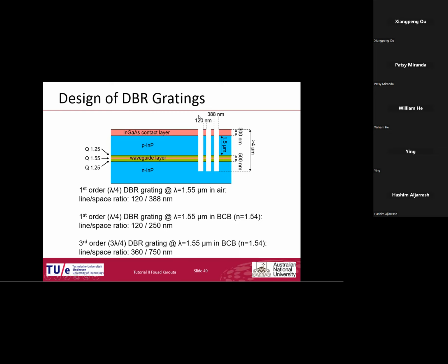So we were interested in getting deep etching of gratings to have an internal mirror on chip. As I mentioned to you last time, when you are doing gallium arsenide lasers, for example, we use the cleaved facet of the chip as the mirror. But in indium phosphide, if you want to have an integrated circuit and you need a mirror to have a laser, then you need to have a DBR grating to play the role of the mirror. So here we tried to develop this technology.